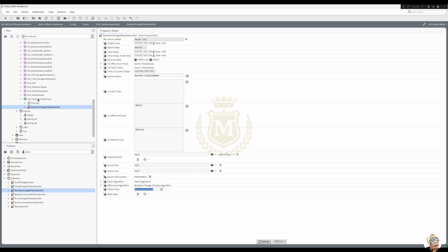Should we put a history on there? We're going to get an alarm and we're going to get alarm histories. But why not? There's no harm in having histories, as long as it don't take up too much space on the station. The default's 500 points, so numeric change. Let's have a history on that. Really? Not numeric, Boolean change. It's me, I'm talking and not concentrating enough.